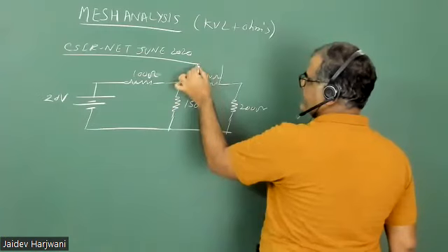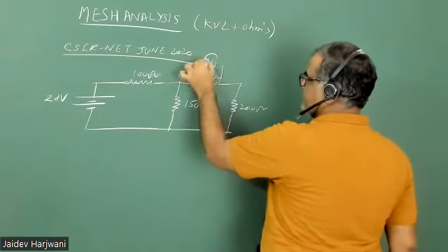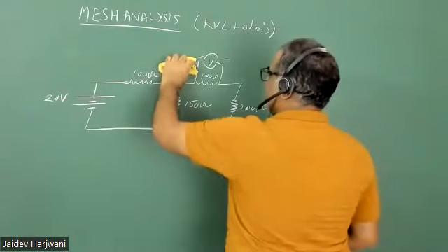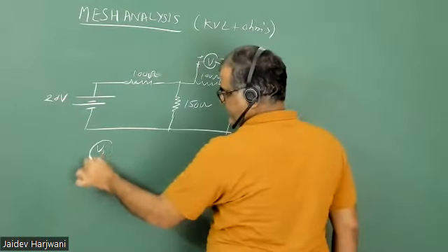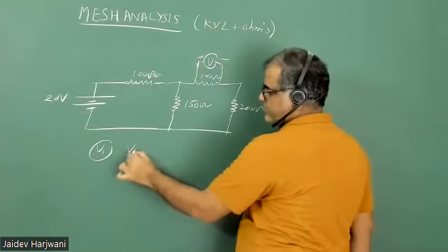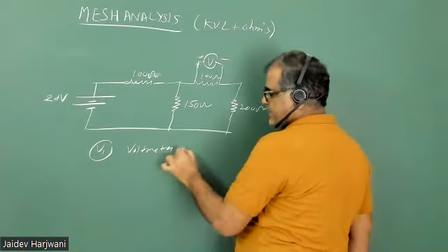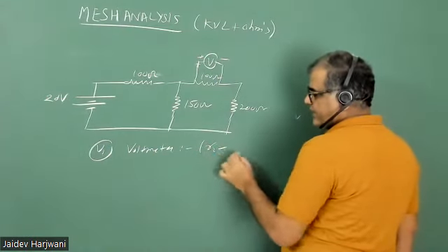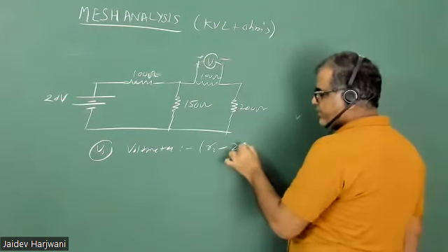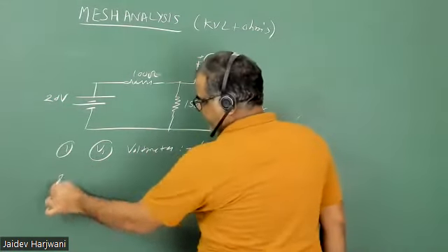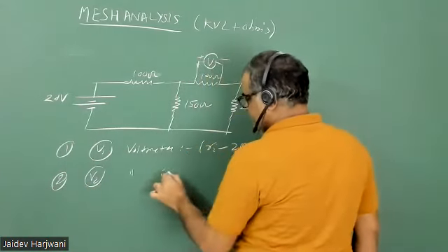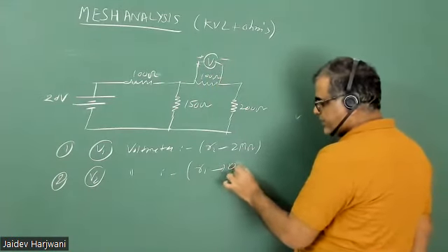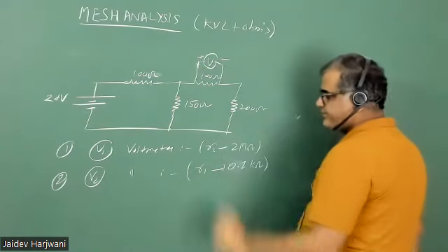Using 2 voltmeters. You have 2 voltmeters, and you are measuring using voltmeters. When you have voltmeter 1, V1, the internal resistance is 2 mega ohm. In the first case, the internal resistance of this voltmeter is 2 mega ohm. And in the second case, for voltmeter V2, the internal resistance is given as 0.1 kilo ohm, that is equal to 100 ohm.